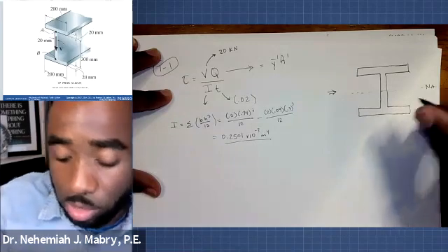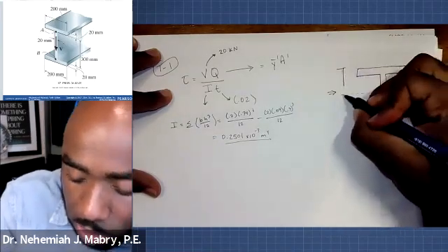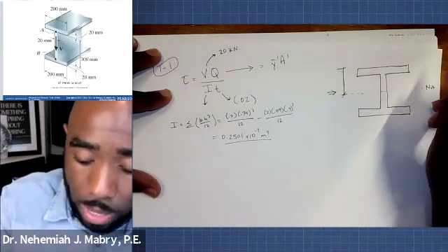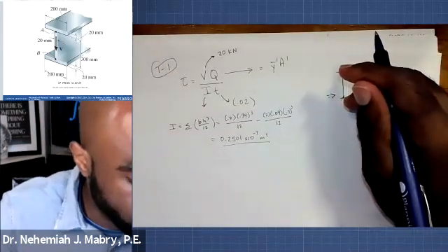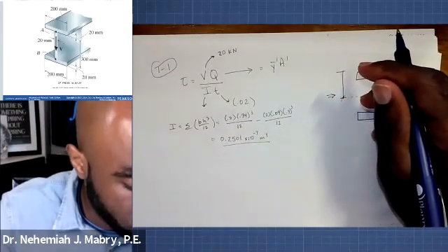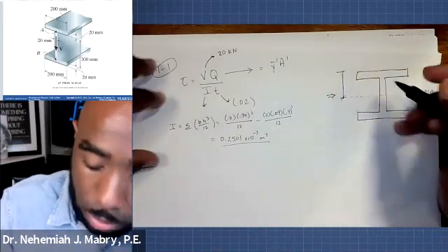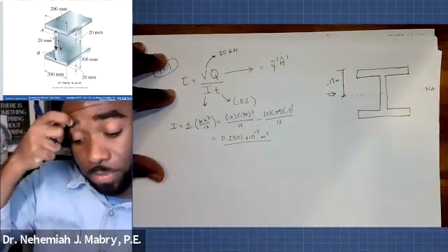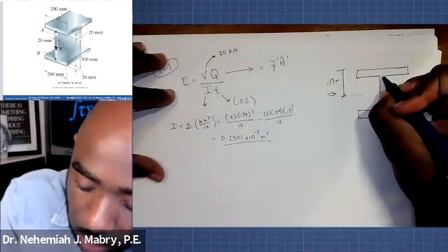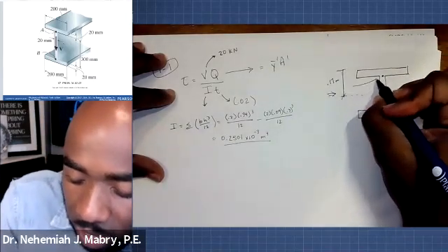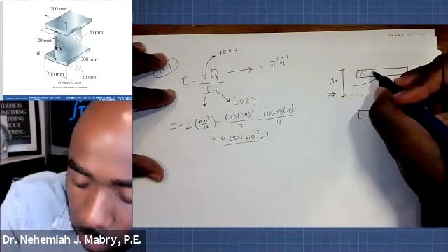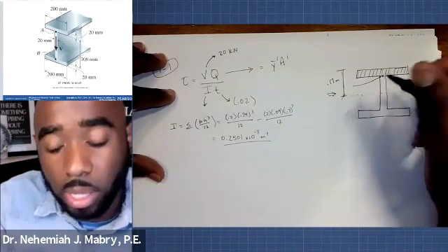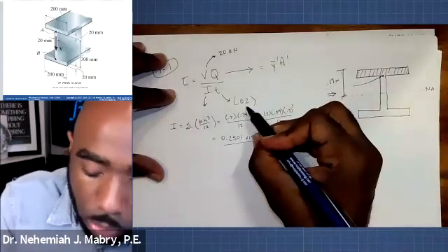That's the neutral axis because it's symmetrical, which means that from the top, the distance to the neutral axis is 0.34 divided by 2. That's 0.17 meters. That's that height. Now, A, the point of interest, is right here at the intersection. Granted, this is an area where it's hard to be precise, so that's why we're only looking at what they tell us. They told us to look at it on the web. That's why we use the 0.02, right?